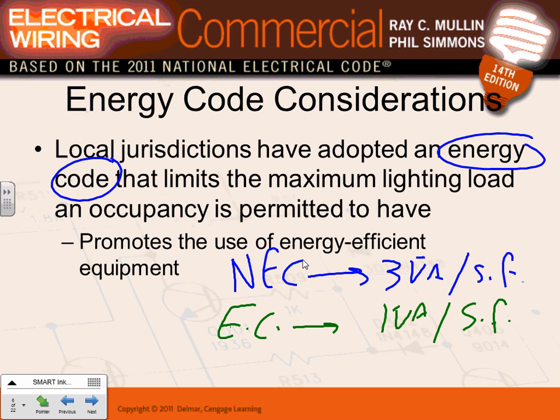Should I go up or should I go down? Now, knowing that this is a lighting panel, and you know for a fact that to meet the energy code you have to go much lower than that, I, as an engineer, can go lower, and I feel comfortable going lower. Does that make sense? Think of the energy code as a comfort zone for you, instead of always going up. For me, I want you guys to go always up. With value engineering, when you sit and look at the big picture, you start going down, because I know the NEC code will give me this, the energy code gives me this. So if I end up with an odd-size panel, maybe I should go down, because I know for a fact my lights are going to be lower than what I calculated.